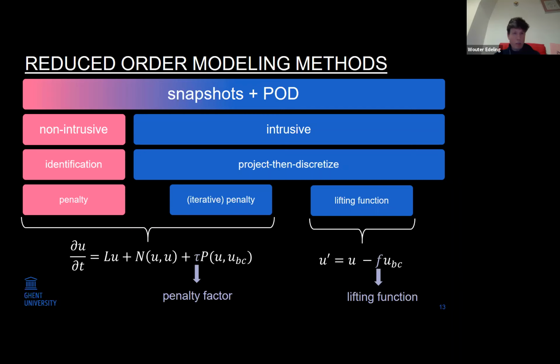You still need a turbulence model if you truncate. Yeah, so what I did, and what you see happening a lot, is that I'm not going to use necessarily the same turbulence model as at full order level, but rather use data-driven approaches, like I do in the non-intrusive approach, to identify some of the variables that are essential for the turbulence part.